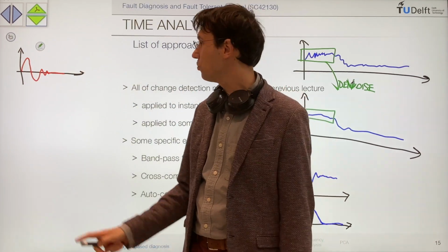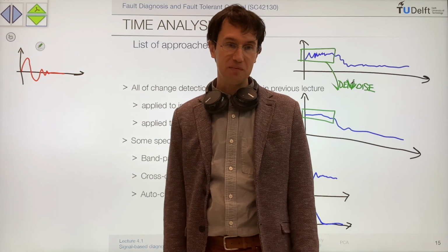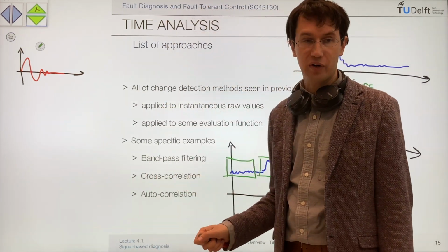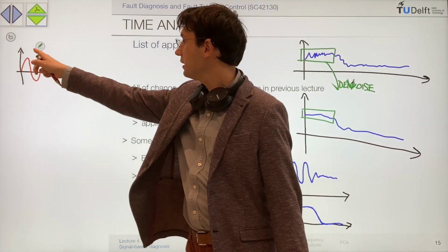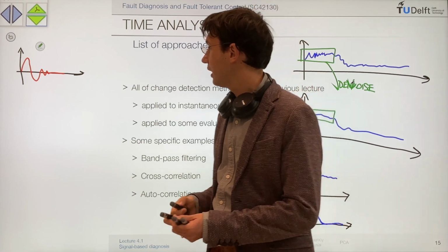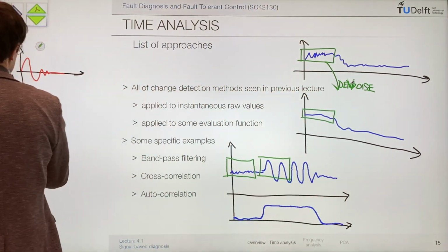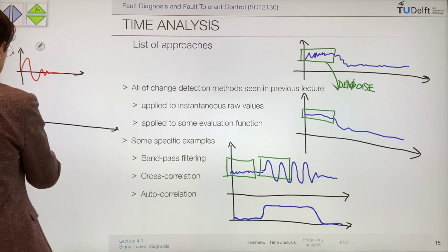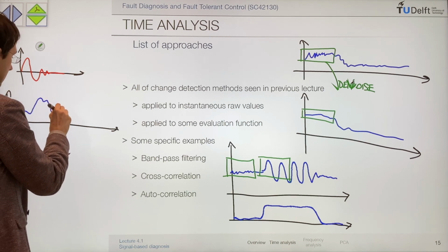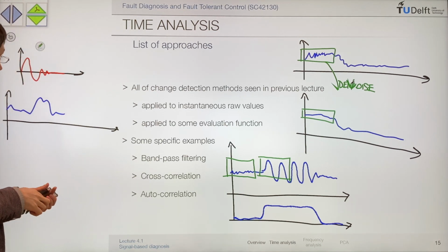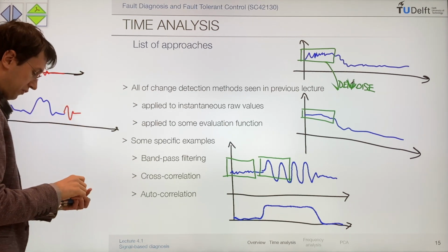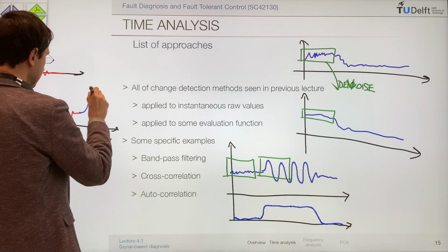If you want to look for this in a signal, the way to do that is by computing the cross-correlation between the fingerprint of the fault and your signal. Let us assume the signal is like this. You have your signal that can change, get big, and so on, but at some point you have the fault happening on top of your complex signal.